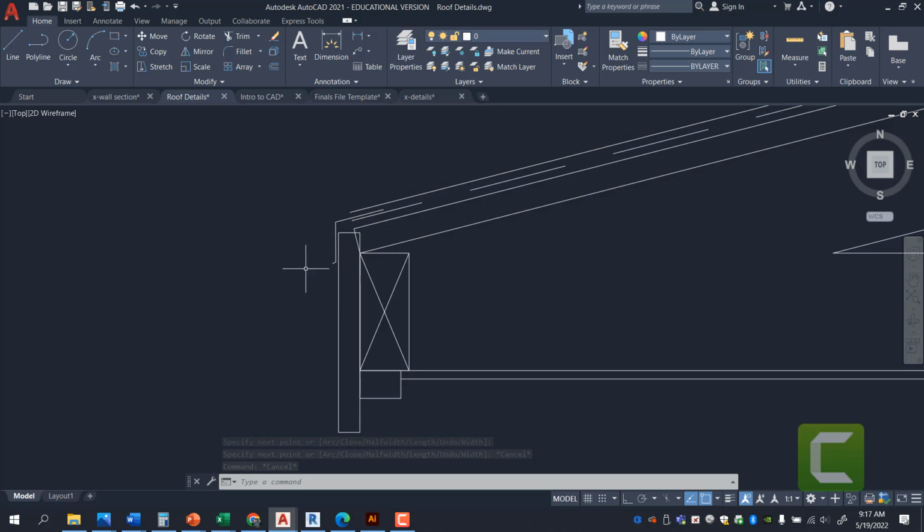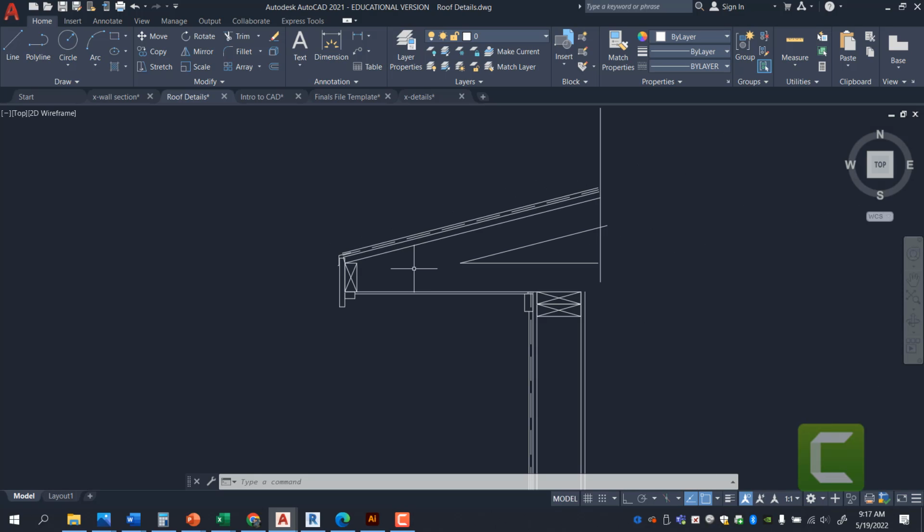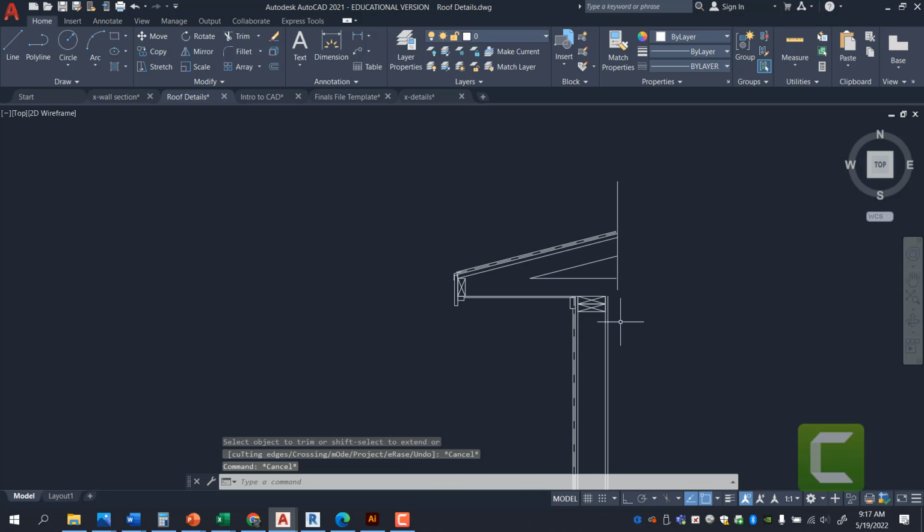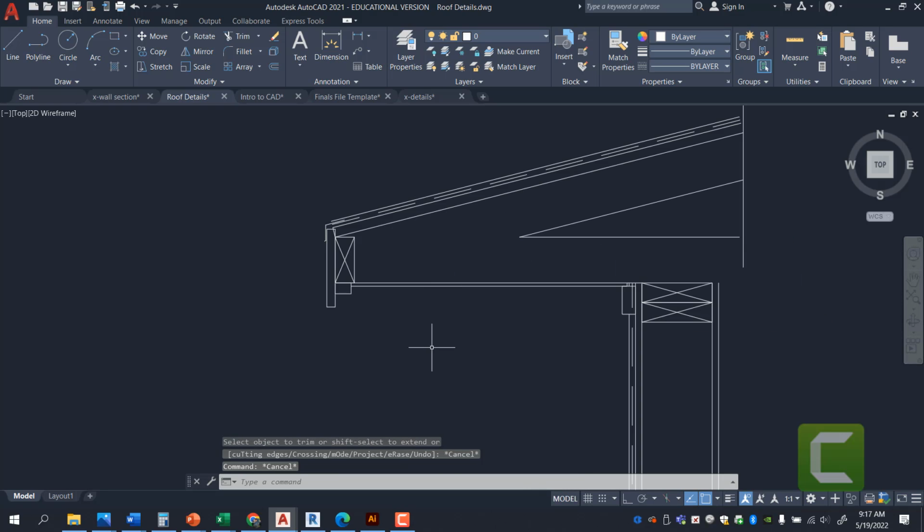It's very important for it to go over your fascia board. Now, if you were to put in your gutters or anything like that, that will get tucked behind this drip edge. And then you'll have a screw that will drive in and hopefully go into your nailer board. And that's how you would do a detail right at the fascia. So this is the basics of what a roof detail at a fascia condition would look like.